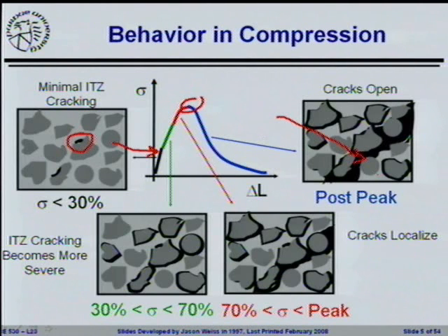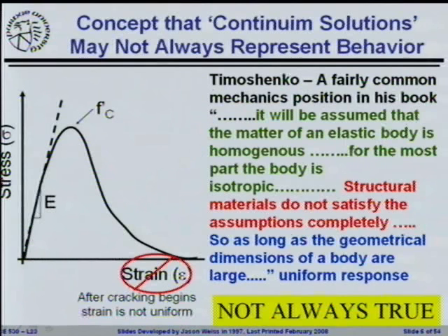The rest of the material is actually unloading, and the cracks are actually closing. So all the damage is going to be localized into one particular spot that you are going to see as the visible crack that's on the surface of the sample. All the other cracks are going to sort of go, when I say go away, they're going to be non-active cracks. They're not going to want to grow. They're going to start to unload. They're simply going to unload in the overall system.